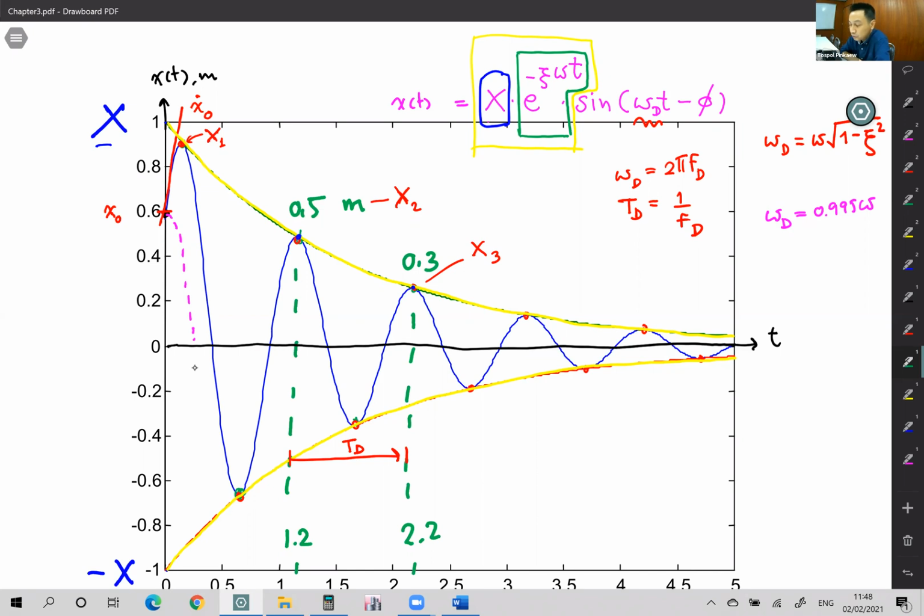But if you design your building using steel structure, if you use wide flange H columns, steel beams, steel shear core, such steel structure buildings, the design codes recommend using a damping ratio of 1 or 2% at most. So the steel structure has a smaller damping ratio than the reinforced concrete building.